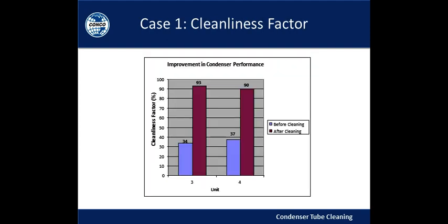Cleanliness factor in the condenser, that's a measurement calculated to assess the performance, went from 34% to 93% on one condenser and 37% to 90% on the second condenser the company cleaned. That's an outstanding result as well.